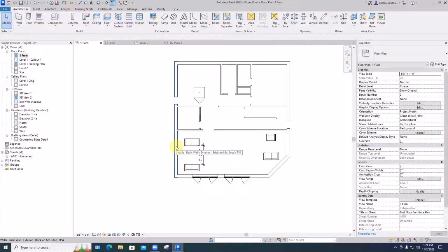I want to talk about text types, text styles, if you will. And the important thing to remember in terms of Revit is, since each view's dimensions and annotations, you create them in that view, they don't get inherited by other views. When you say I want stuff a 1/4 of an inch high in this particular view right here, which is 1/8 of an inch equals a foot, Revit does whatever it has to do to the text so that when that's plotted at 1/8 of an inch equals a foot, it will always be that 1/4 of an inch high. Change the scale of that and put it on a sheet, it will still be a 1/4 of an inch high. It's just entirely consistent.